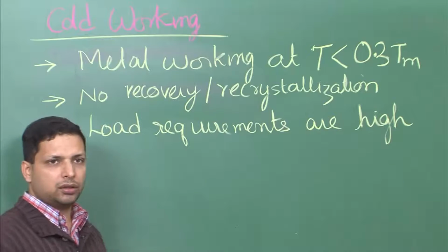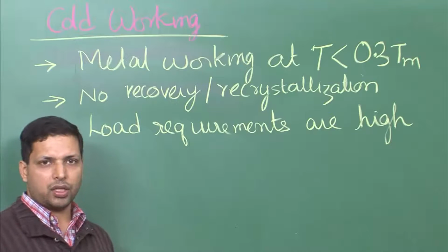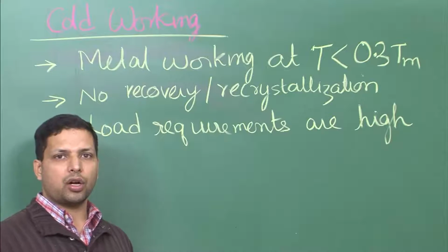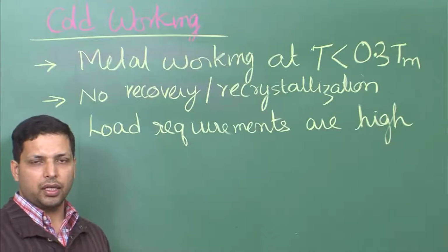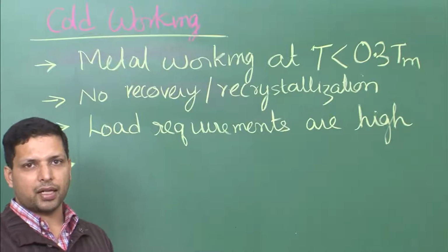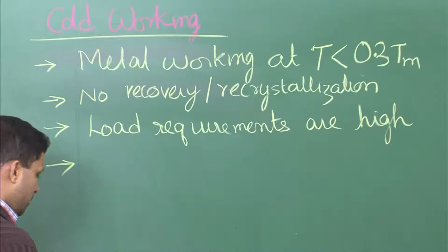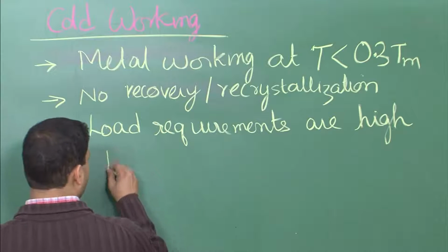On the other hand, because you are doing it at a very low temperature, the expansions are not there, or basically you do not need to see how much the material will contract after you have cooled down, because you are already at a very low temperature, and hence what you get is better dimensional control.